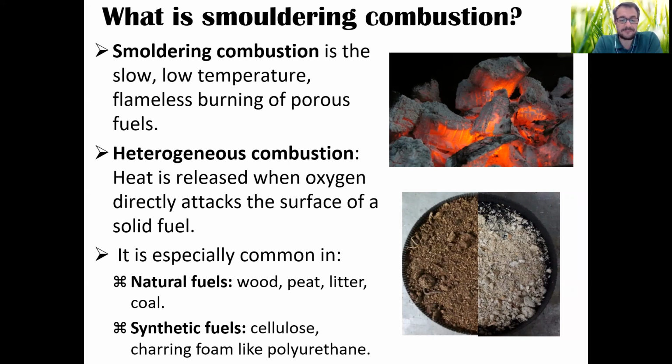It makes the amount of energy that is released significantly lower than a flame. It makes the temperature lower. It makes the spread slower, and it makes the emissions, the smoke produced from smoldering, very toxic. It has a very strong smell. Some people really like it, but it means that the smoke contains a significant amount of hydrocarbons and complex chemical molecules that can, some of them, further burn and even release more energy, or attack biological systems and life.